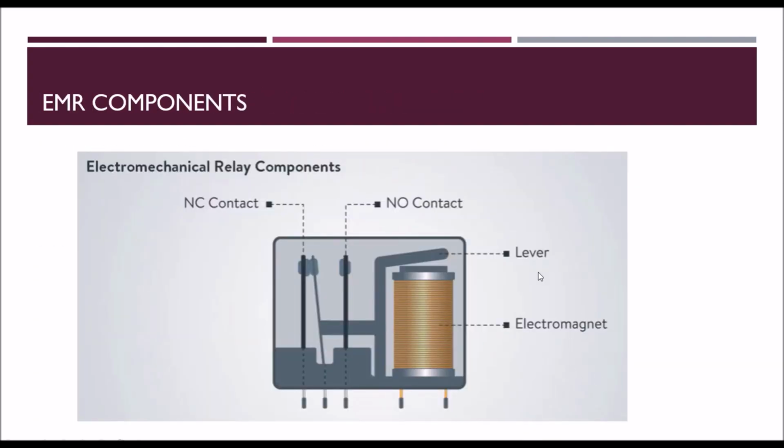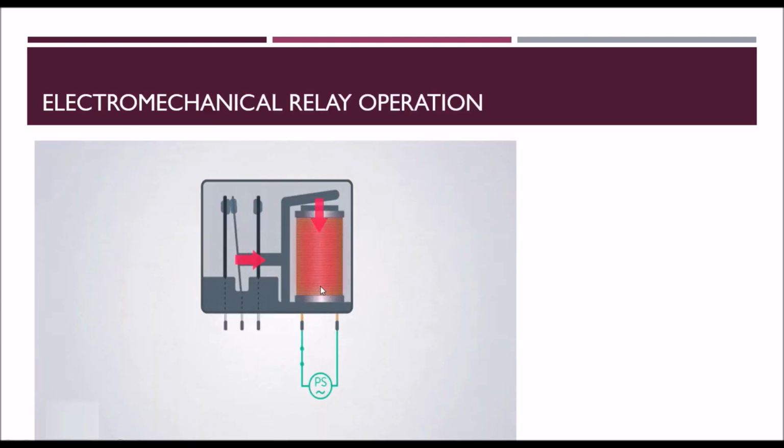See here, this is another way you can understand. There is a middle contact, which is the common terminal. So it has three terminals here: the NC contact, and the normally open contact. So what happens when the coil is energized? Here the coil is shown as AC, but it's okay, DC also. We are discussing only DC here. When the coil is energized, the middle contact moves away from the NC contact and makes contact with the NO contact. So this is the understanding, and the pins are here where we can connect the load.